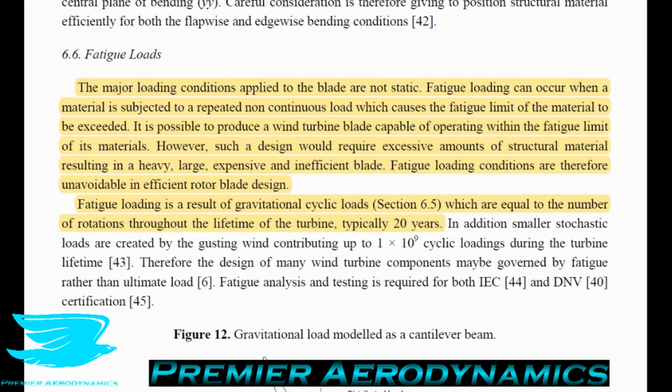Now, there's a more complicated phenomenon that happens. It gets stiffer because what they call dislocations, which are at the atomic and molecular level, get intertwined, and then it gets stiffer and then it eventually breaks just due to becoming weaker over time. I'm not going to go into that because it's like a whole course in itself, but that's just the general physics behind it. They say fatigue loading can occur when a material is subjected to a repeated non-continuous load, which causes the fatigue limit of the material to be exceeded.